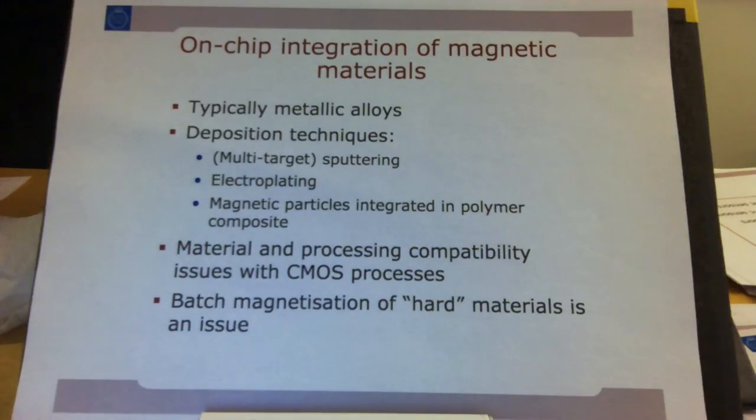However, both the materials and the way of processing them, that means their etching or their machining, will typically not be compatible with CMOS processing, and often these materials will not be allowed into a clean room because they will be poisonous for other clean room processes. So there you have a generic problem. So you have how to combine that with the batch manufacturing inside the clean room.